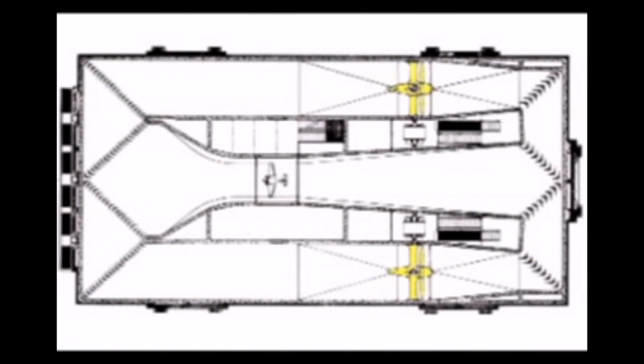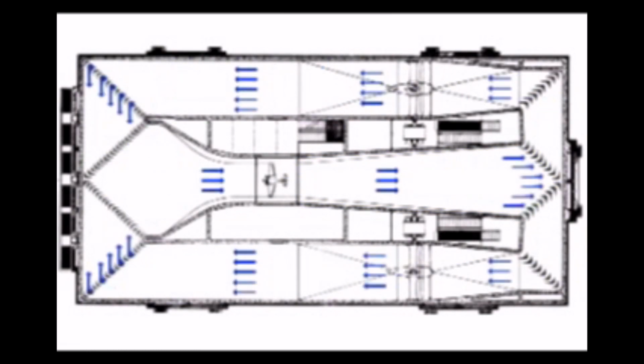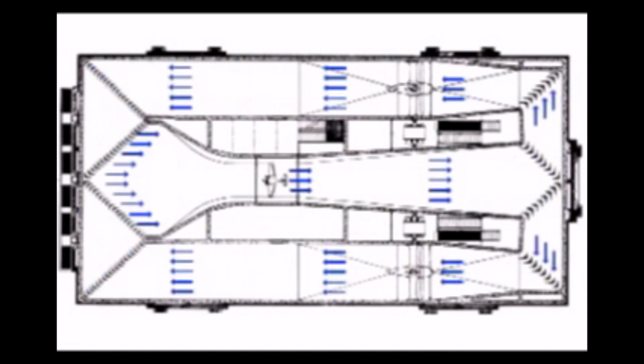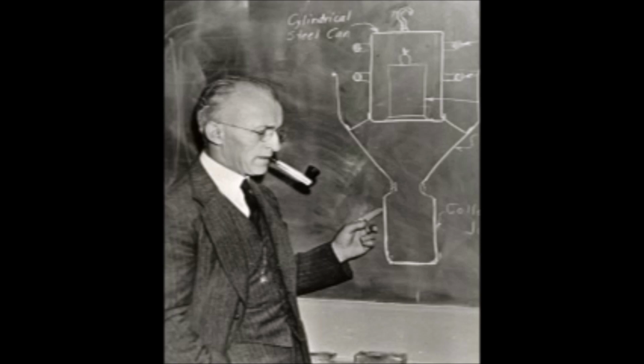The Kirsten Wind Tunnel is a closed-circuit double-return wind tunnel. Two fans located in the circuits on either side of the test section can simultaneously generate wind reaching 200 miles per hour. The wind moves around the corners with the help of curved turning vanes. It is then straightened and funneled through the bell mouth ahead of the test section, thereby increasing the wind speed 6 times. After passing through the test section, the wind slows down, passing through the diffuser for its return trip to the fans. The overall momentum of the wind is conserved, giving the tunnel a dramatic power advantage over open-circuit tunnels where the wind is vented to the outside.